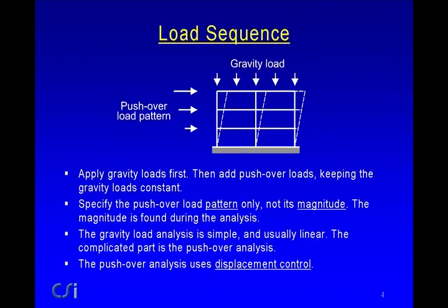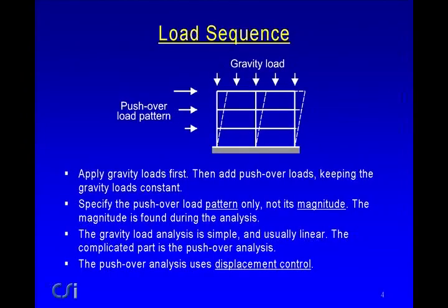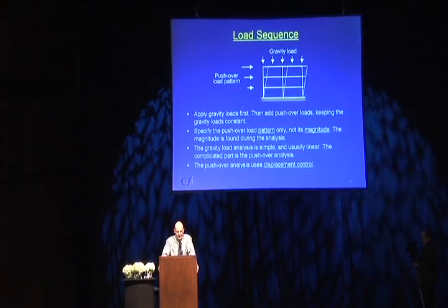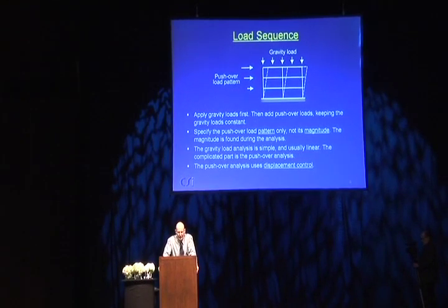We're talking here about a static pushover. So the load sequence is to apply gravity loads first, and then, keeping the gravity loads constant, add the pushover loads. You specify the pushover load pattern only, not the magnitude. You find the magnitude during the analysis.